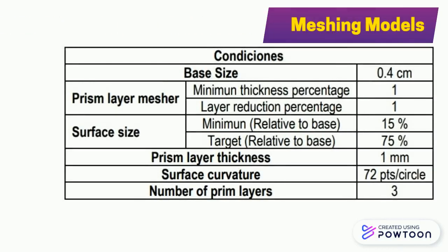For the selection of the meshing models, polyhedral cells were used in order to make a good discretization of the control volume obtained. Additionally, the prism layer model was chosen to obtain a good transition from the turbulent zones to the laminar zones near the walls. On the other hand, the surface remesher was used to obtain a mesh that meets a high cell quality and improve those axes or corners that generate discontinuous figures when the CAD is imported into the program